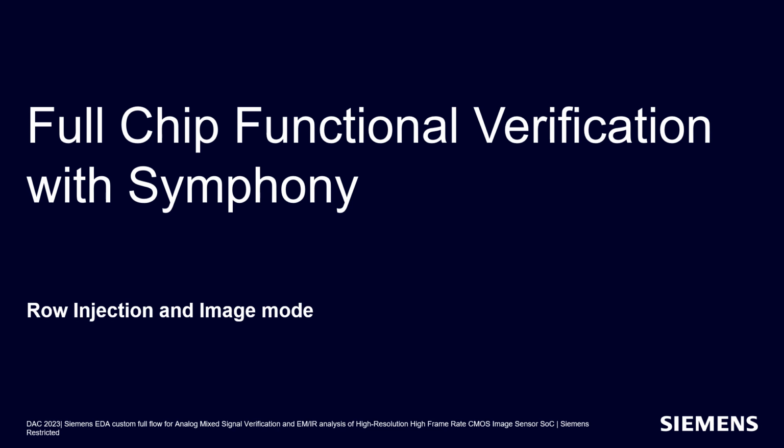Next, we switch gears and look at the mixed signal test case for our complete top chip schematic for our cinematography image sensor. Our goal here is to do a full chip functional verification, and we use the Siemens Symphony mixed signal simulator to achieve our verification objective.